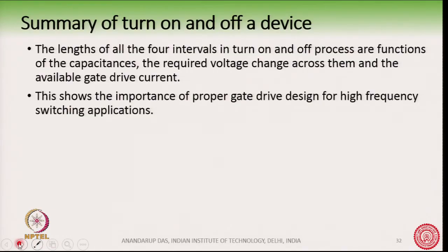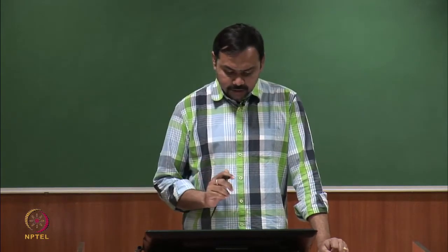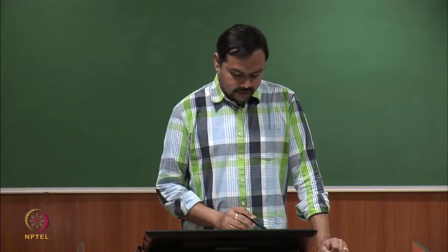So, this is what I wanted to summarize, that the length of all these 4 intervals in the turn on and turn off process are a function of the capacitors, the required voltage change across them and the available gate drive current. So, in a gate drive design for high switching frequency application, it is important to properly choose these components.